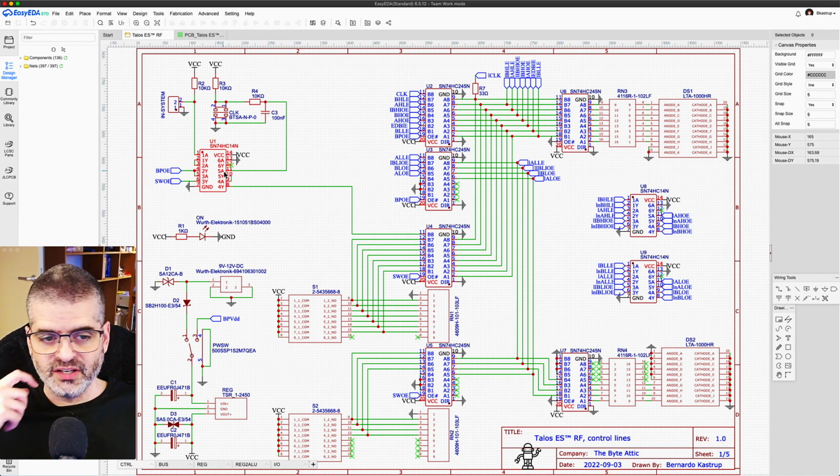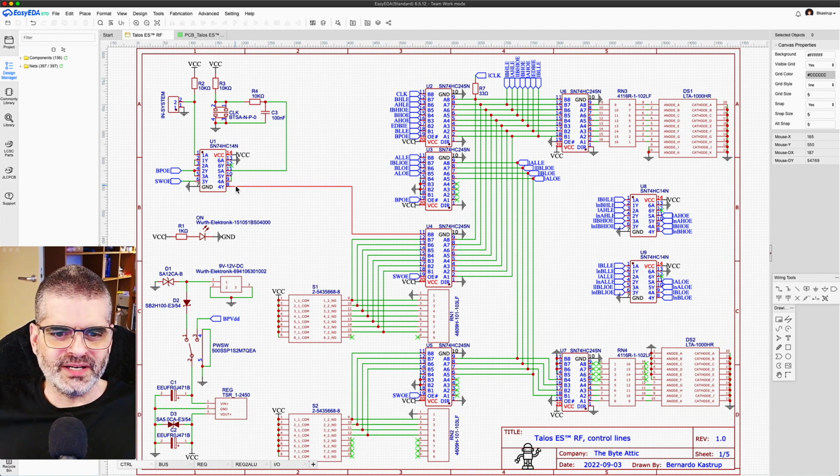Here the Schmitt trigger is important because this whole thing here is a debouncing circuit. And in a debouncing circuit you want the Schmitt trigger. So it is inverted once, inverted twice. In other words, it's not inverted, it's just cleaned by the Schmitt trigger, and goes into this buffer as the